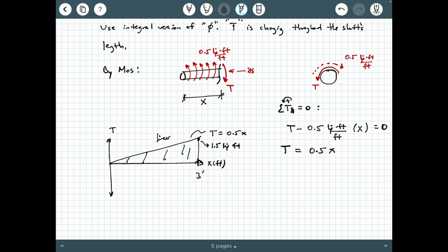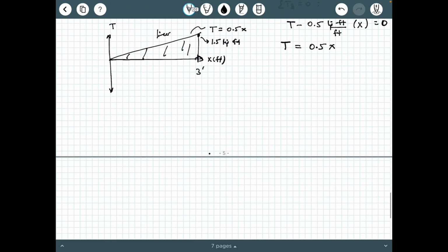I think for this application, method of sections is better, okay? So I would prefer method of sections, but you might see a book or another reference that uses a torque diagram here, all right? But again, I would use this method of sections. Regardless, what do we do next? Well, we're going to say phi of A with respect to B, so that means the angle of twist of the free end A with respect to the fixed end B.